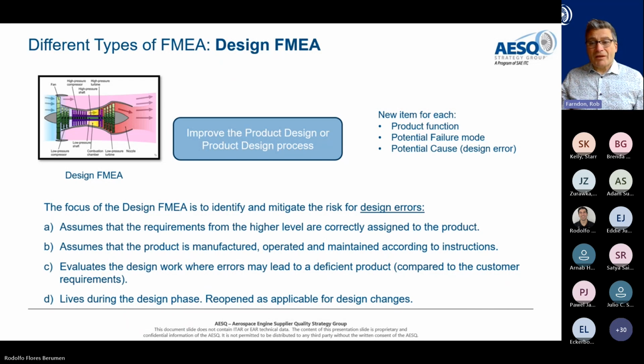As such, the occurrence ratings and all of the scoring mechanisms that go with the DFMEA actually mean very little outside of the DFMEA. They inform other processes, sure, but they are not absolute hard and fast numbers that relate either to the safety or the reliability or the quality of the product. They're just an indicator that indicates where we need to focus to improve the design.